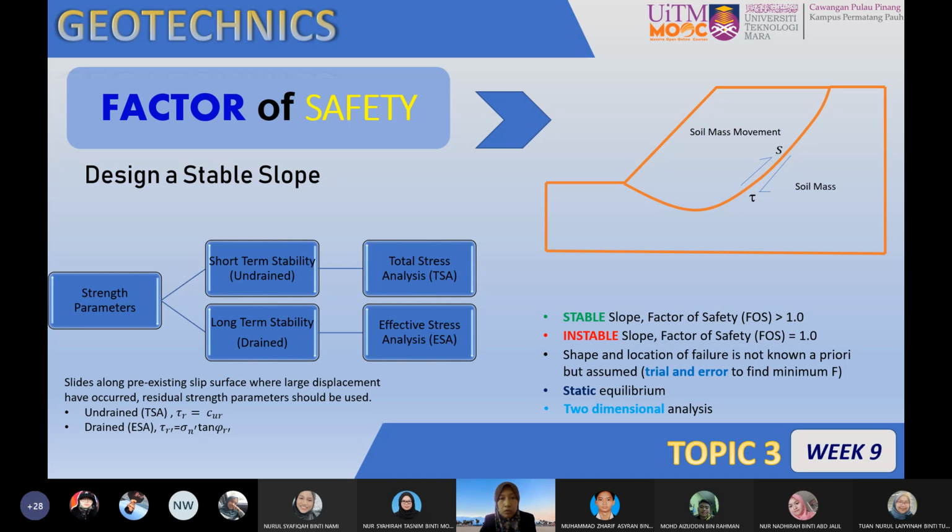And at this time we also have the resisting force that is due to the shear strength of the soil, cu, multiplied by the length of the arc. So the length of the arc along the slip circle, the slip surface, together with the undrained cohesion, tries to resist any slope mass movement.